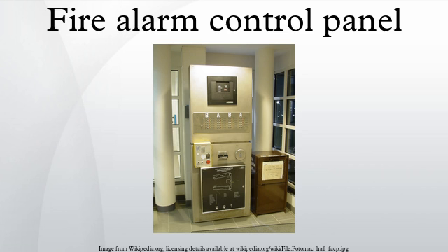System functions. There are many functions on a fire alarm panel. Some of these are: System reset. This resets the panel after an alarm condition. All initiating devices are reset, and the panel is cleared of any alarm conditions. If an initiating device is still in alarm after the system is reset, such as a smoke detector continuing to sense smoke, or a manual pull station still in an activated position, another alarm will be initiated.